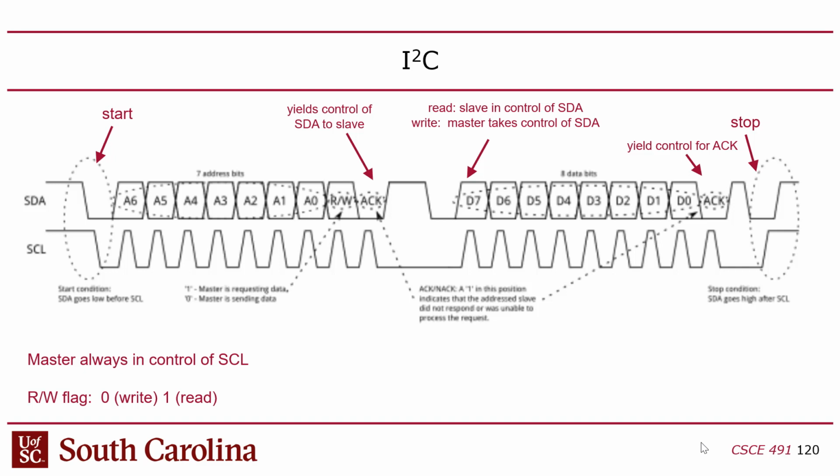Then you might have talked about these things called latches in 211. A latch is level sensitive, right? Where basically when the clock is, say, high, data will transparently flow through it, and then when you drop the clock, it freezes whatever was in there, whatever the last thing that passed through, right? That's level sensitive. And we also talked about this in terms of interrupts too. Interrupts can be level sensitive or edge sensitive, right? Well, I2C uses a level sensitive clock. It uses a latch-based clock.